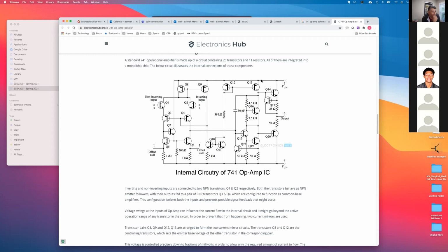At this level, it's important that you're aware that they exist, and they are like the NPN. You want to operate them in the forward active mode. You don't want to saturate them. The voltages are flipped. They tend to be much slower than NPNs, and their beta, the current gain between the collector and the base, also tends to be lower. So they're just not as good as NPNs for various reasons.